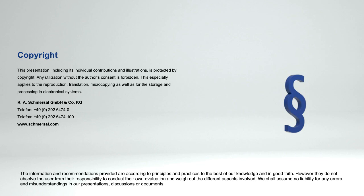Very good. Marcelo Caso from Bayersdorf, we wanted to know, is the performance level applicable for the component or for the overall machine? The performance level is looking at both. You can get a performance level for a component, but you're not looking at the overall machine. You're looking at the overall safety function. And here's what I mean by that. If we look at the previous example that I gave with the key interlock, the safety controller, and the two mechanically linked contactors to shut down the motor, the key interlock is our input. The safety controller is our logic. The two mechanically linked contactors are our output.